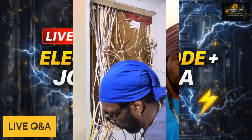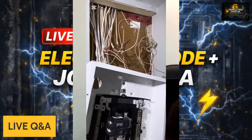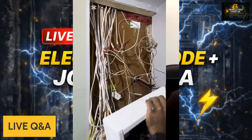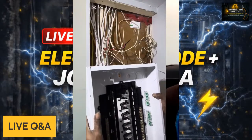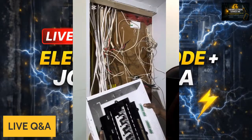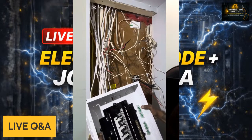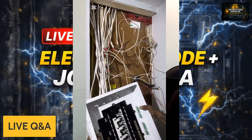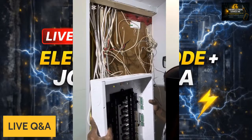And this is the new panel. But I'm going to be taking this panel and flipping it the other way because the main comes in this way. So for that reason, I have to flip my panel the other direction instead of the normal way. This is allowed because there's a code rule that states that your breaker has to be a certain height. This is within my certain height, so I can take this panel and flip it the other way, and that's exactly what I'm going to do to make this work.